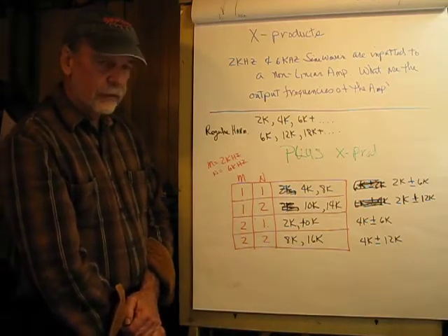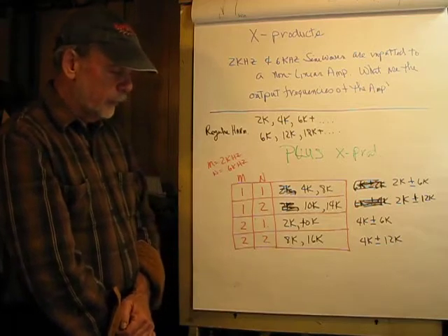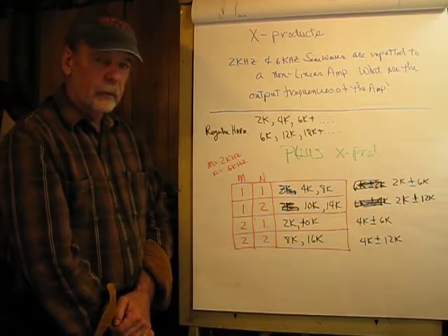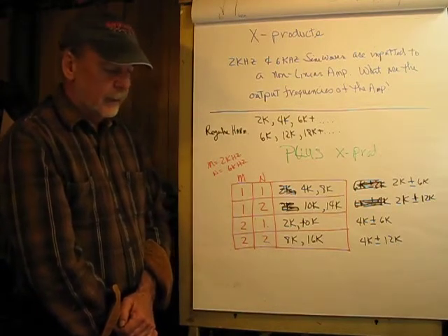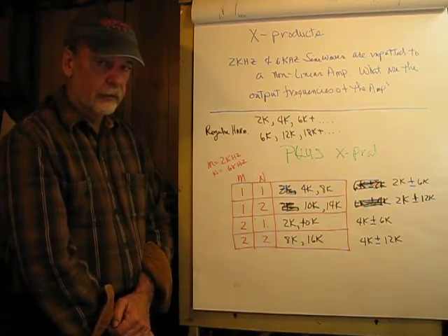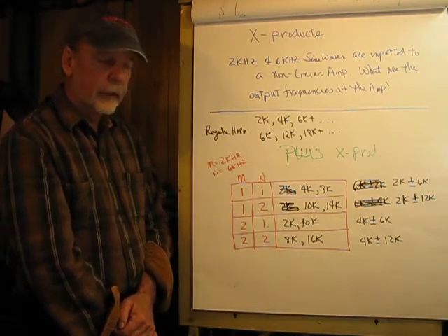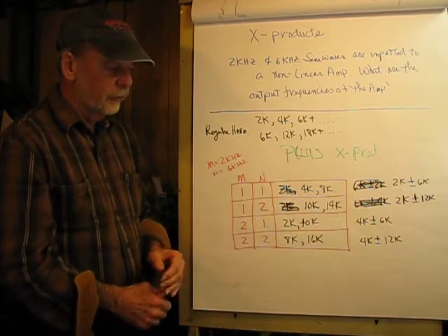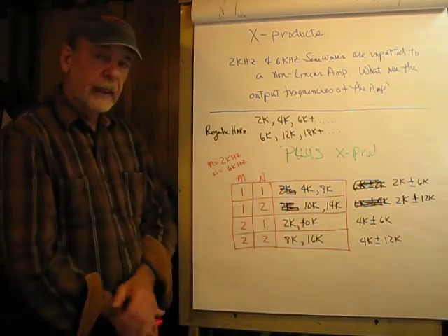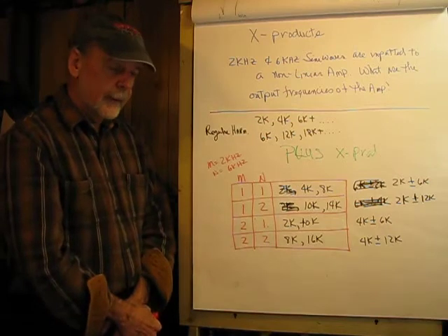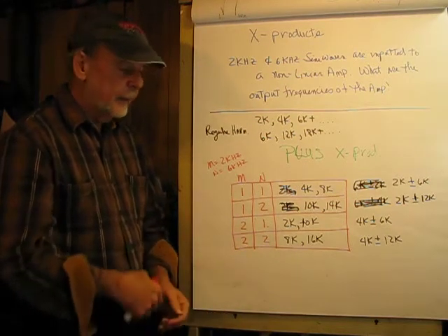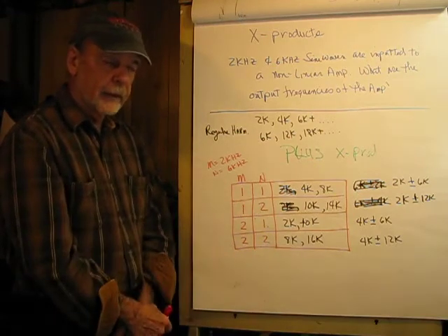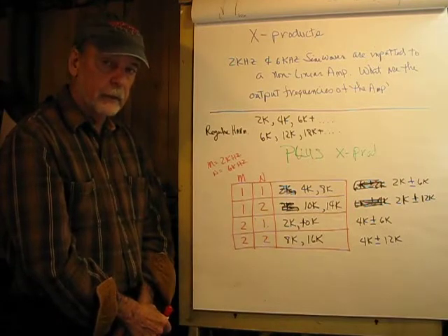Many times these are very, very necessary. For example, if you tune in a radio station, the antenna feeds a device called a mixer with a whole bunch of different frequencies. And another device called a local oscillator generates one sine wave that's higher than the frequency that we want to tune to. And these go into this very nonlinear device, and we get the sums and differences, and we take one of those differences, tune it, get rid of everything else, amplify the heck out of it, detect it, put a diode in series with it, connect to an audio amplifier, and we have an AM radio.